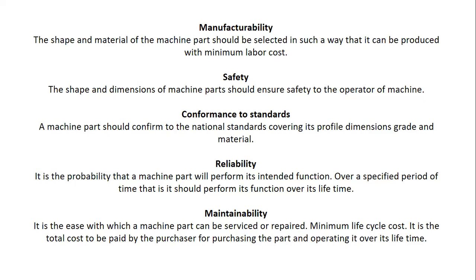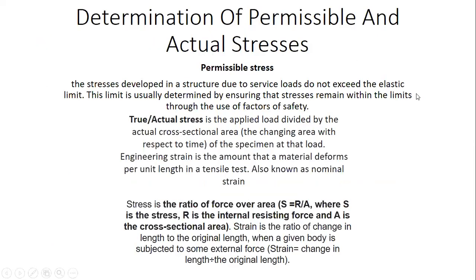But for parts that are more difficult to get, if you need to do a change or a repair on your component or machine and you have to ask for the parts from abroad, you have to impute the cost involved in importing some of these parts. Then look at the time that this would take. If you impute all of these, you will see that most companies would prefer machine parts that are easily maintained. So maintainability is very important.